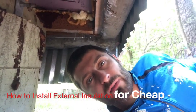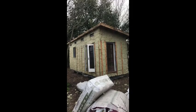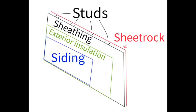The concept of external insulation. External insulation takes place when you have insulating properties outside of the framing and the sheathing of the house. So the sheathing and the framing are within the insulated area of the house. The reason that external insulation has become more popular nowadays is because of the concept of thermal bridging, and it's a lot more efficient to have external insulation to stop thermal bridging from happening.